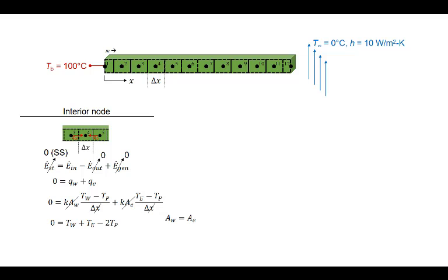The temperature to the west plus the temperature to the east minus 2 times the temperature of the volume of interest. These things must add to be 0. Substituting on our counter variable m, this means that the m-1 node, 3 in this case, plus the m+1, 5 in this case, minus 2 times the mth node, 4 in this case, must be 0.